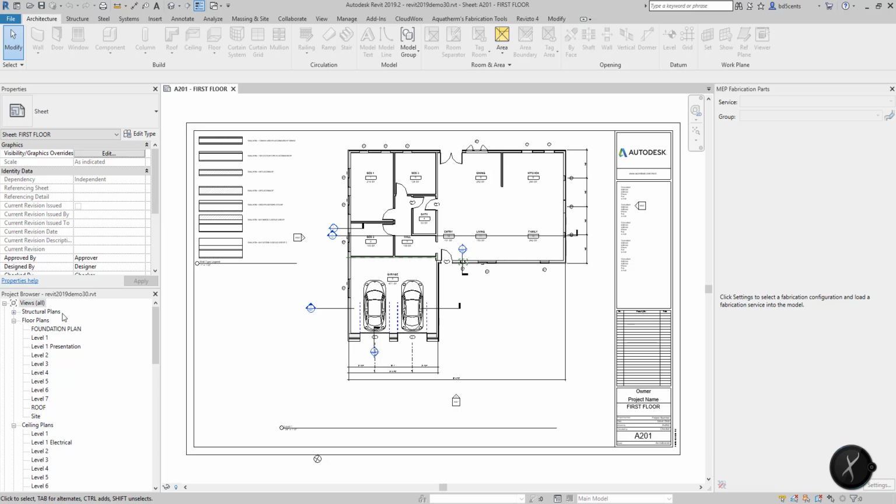We will use the gyp board, also called drywall ceiling, to hide the second floor subfloor, to attach ceiling-based elements like lights, ceiling fans, air conditioning diffusers, and smoke detectors. We will also use the gyp ceiling on the second floor. It would be attached to the bottom of the roof joist. So for this example, we're going to make a 5/8 inch drywall ceiling.